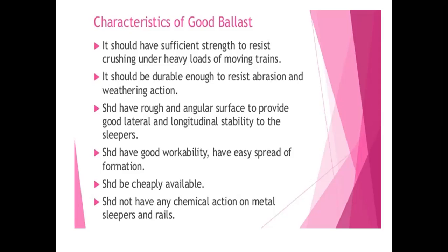While talking about good characteristics of a ballast, these ballasts can't be crushed by continuous applying of load by the moving trains, and can't show any chemical actions on metal sleepers and rails. These are very easy to work with and easy to spread for the formation bed. And they should also be cheaply available.